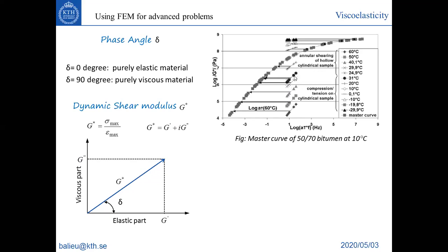So we have a lot of different experiment results, and we can plot a certain master curve here. This master curve has been plotted for 60 degrees, I guess. And there is some formula written in the frequency domain. On this, you can characterize your G_i and tau_i.